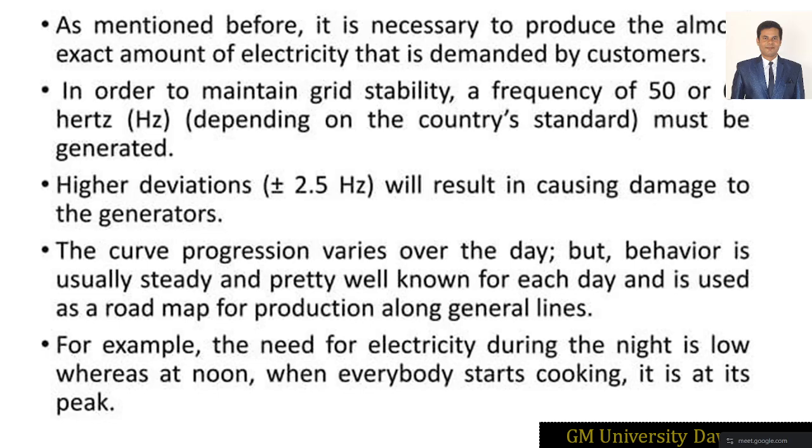Okay, and also another thing is that from the storage of energy we can make the grid more stable. Okay, in India there are 50 Hz cycles, so we have to maintain that frequency. Because frequency is very important, right? The phase angle of the generation and the load angle of the load side should be almost the same. There should not be deviations. If there are, frequency instability occurs, and frequency instability should not happen.